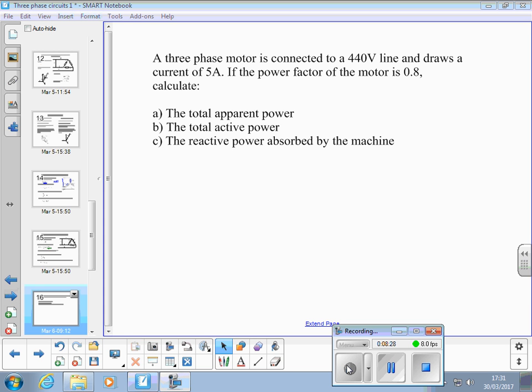In terms of a motor, you're going to assume that they've wound all 3 windings at least somewhere in the same ballpark, resistance and inductance wise, otherwise it wouldn't run very well. So the assumption here, if you're connecting a 3-phase motor, is that it is balanced. The only way it wouldn't be is if you had a phase miss and one winding open circuit or something like that, or a partial short circuit in the windings.